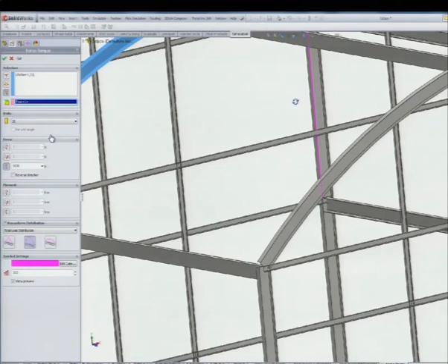I have to put all the three members in the middle, and the load in the other member. Yes, that's right. This is only an example to show how to introduce the load, right? Yes, but if we want to run this example with all, we have to take into account that we have two different load stages. What you said, we have this load from the wind in this way, and we have a longitudinal wind also, right? Yeah, this is only an example.